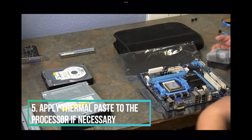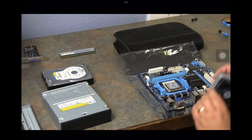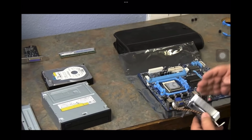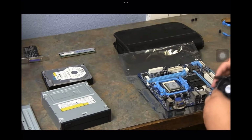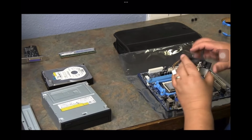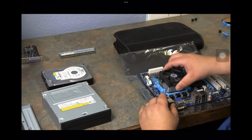Step 5. Apply thermal paste to the processor if necessary. Put a small dot, around the size of a grain of rice or a pea, of thermal paste on the CPU. Adding too much thermal paste will create a mess, such as getting paste into the motherboard socket, which may short circuit components and decrease the motherboard's value if you plan to sell it later.